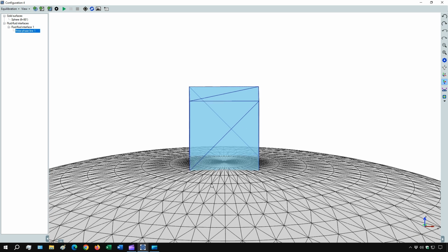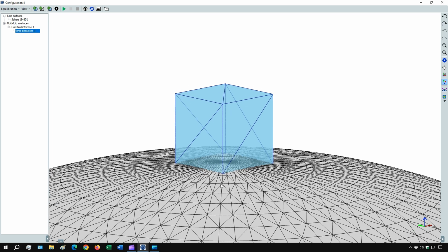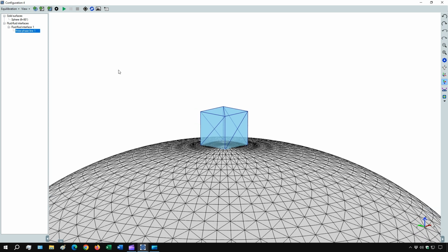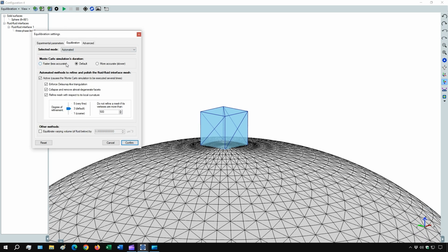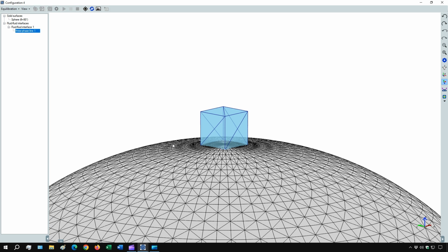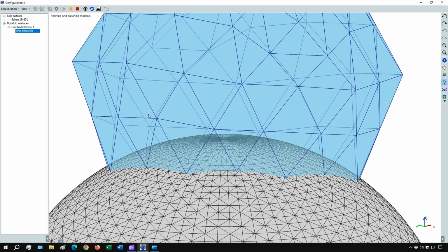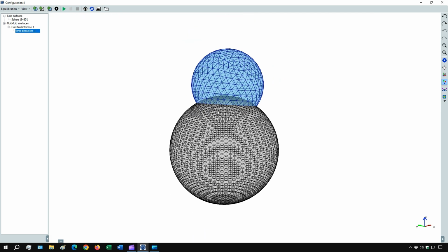So, if we wanted to simulate a droplet with a volume of exactly, say, 1 cubic micron, we just need to enable the option to increase the droplet volume and set the volume variation to 0.999 cubic microns. Then, after launching the equilibration, the obtained droplet will have, with a very good approximation, a volume of exactly 1 cubic micron.